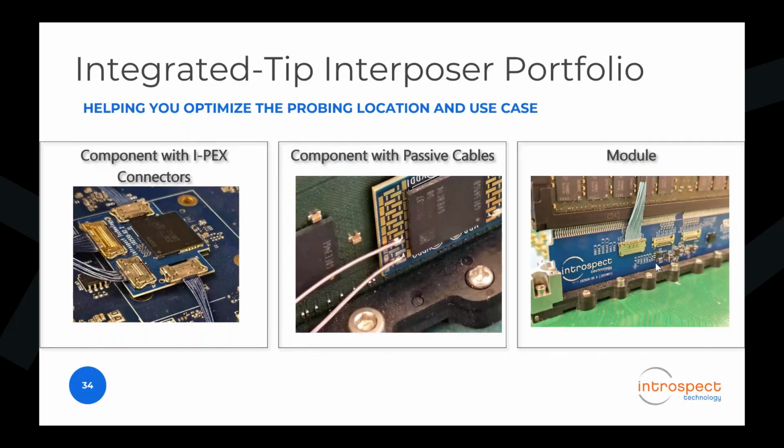Typically, it does it all automatically. The only requirement is you need to have traffic running in your system, then the analyzer will sweep its VREF, like its reference voltage, very much like the receiver, right? So it will sweep the reference voltage to center the range of the eye.